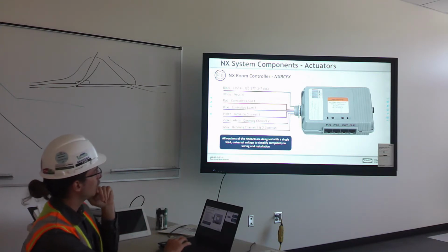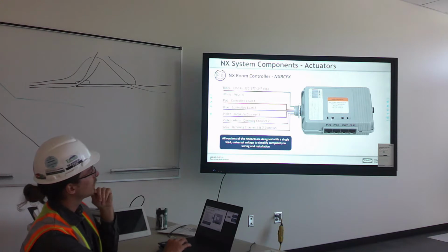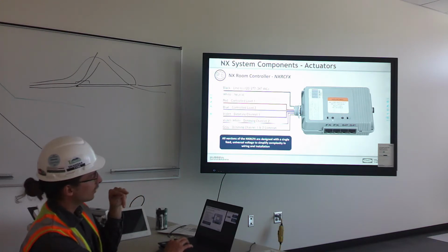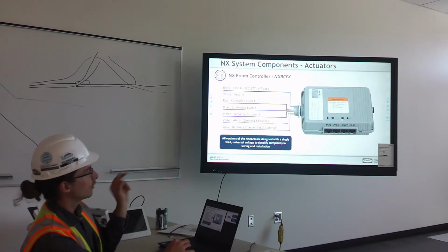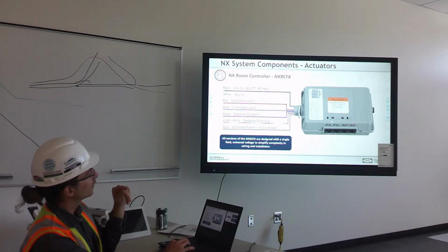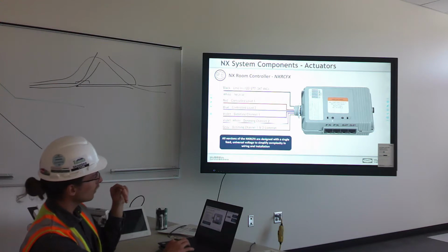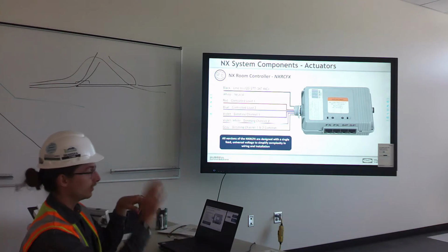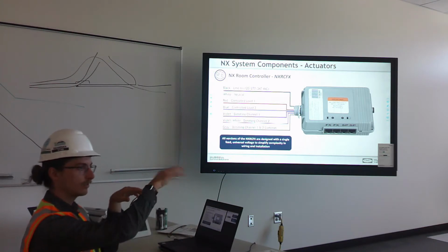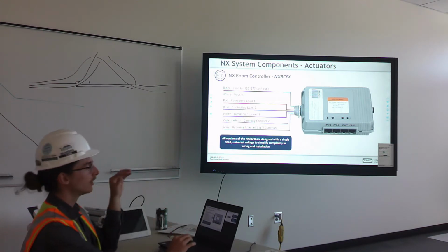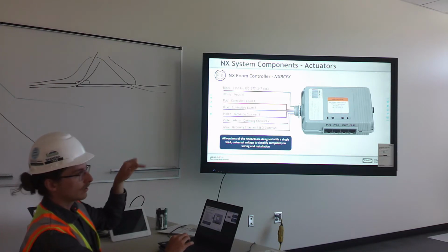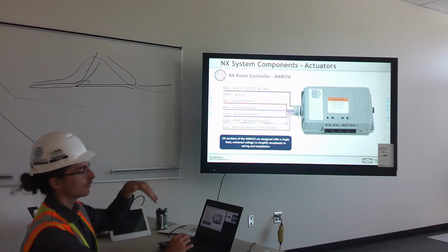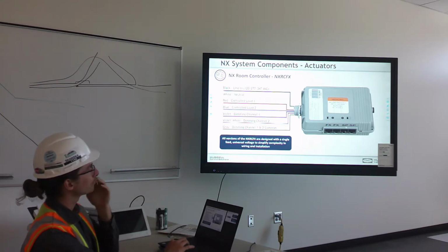We've also got these override buttons here. So whether it's a 2 or 1 relay controller, you'll still have both of those buttons. If it's only a 1 relay, only your A button is actually going to do anything. You just click it, it'll turn the relay on and off. So that's a good way to see what that controller is connected to, what fixtures it's switching. If you hold the button down, it'll move the dimmer up and down. So then you can see what that dimmer output is controlling.